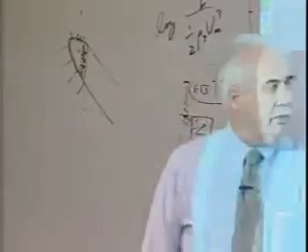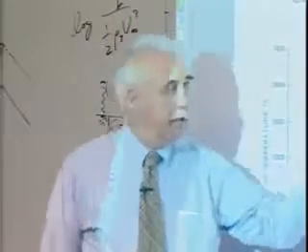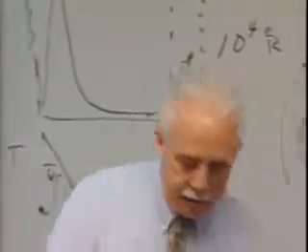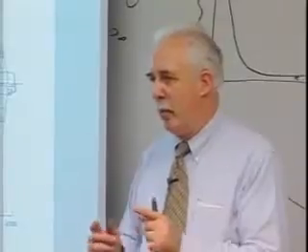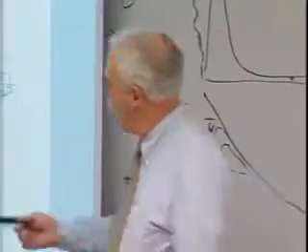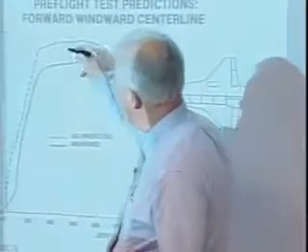See, we come much closer together here in time, okay? This is predominantly the chemistry. At this time, this non-equilibrium relaxation distance is about 6 inches, okay? Now, we're not into radiating gas, but we're certainly not into equilibrium. That is also a factor, and that is not well included even today, in my opinion, other than through correlations of shock and what's going on here.